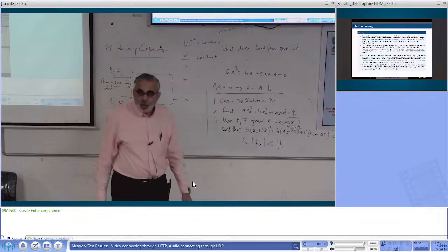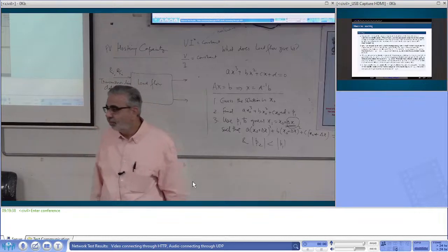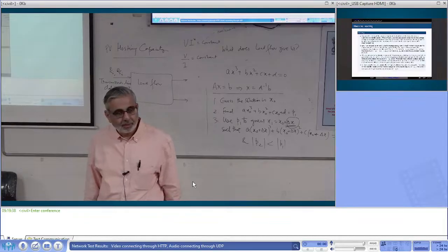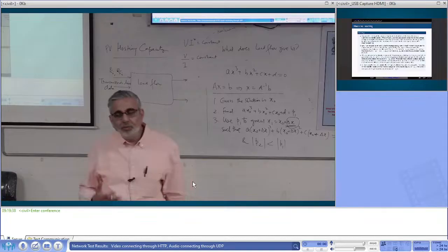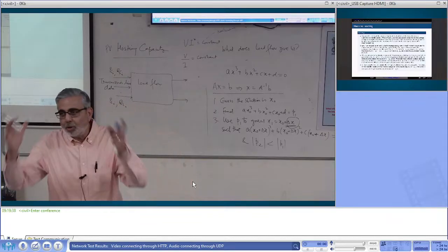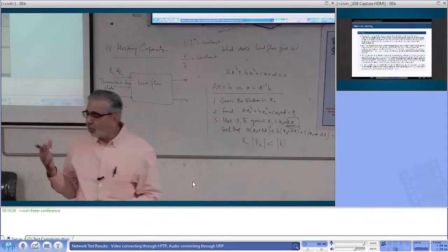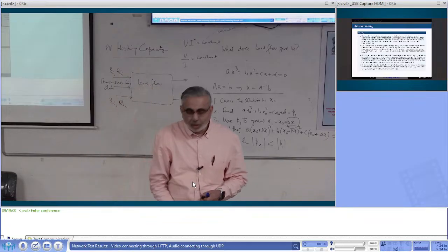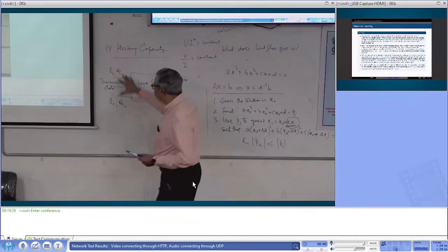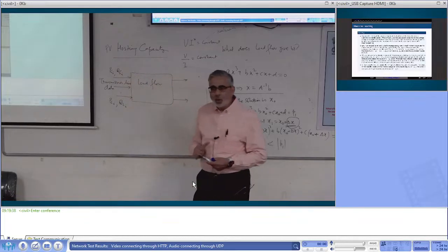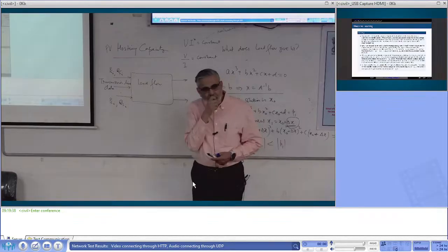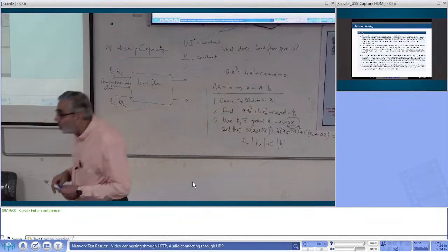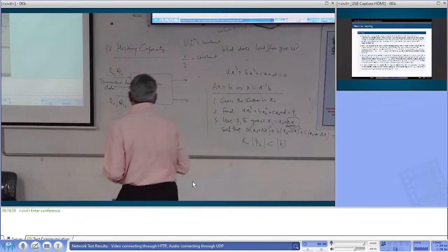You will need to have the loads. If there are no loads, we can't model the network, because what we were modeling as constant impedance, now we are modeling as constant current or constant power or whatever. So that can be covered in this. So this is our input data. What do we expect at the output? Voltages.